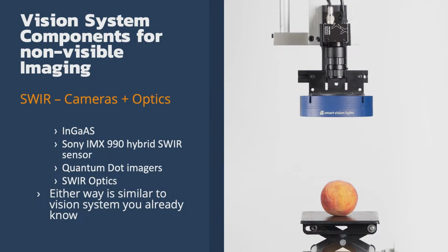This sensor has an InGaAs sensor and pixel readout structure, but the back end of the shift registers and actually reading out, or clocking out, of the image is CMOS, and they are copper on copper bump bonded through a special technology developed by Sony to make a lower cost sensor.